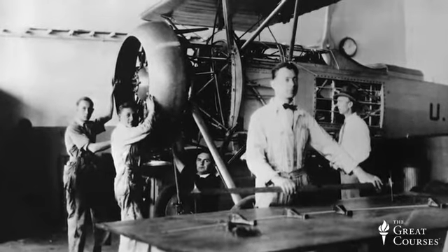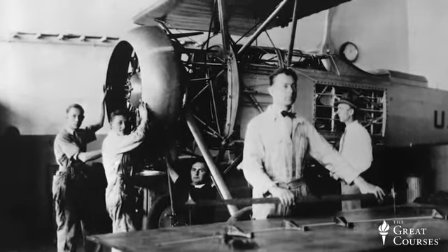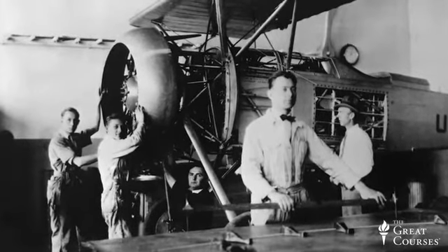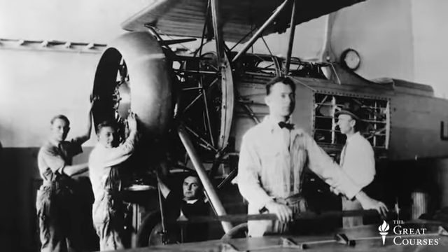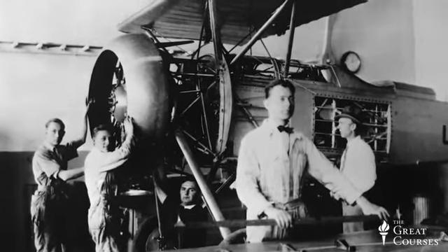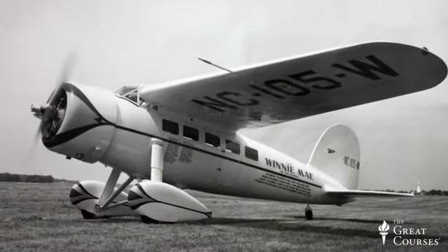Whereas the AT-5A in its baseline configuration had a top speed of 118 miles per hour, with the new NACA cowling, they hit a top speed of 137 miles per hour, a 16% increase in max speed. And on top of that, there was absolutely no change in the cooling of the engine, as the oil temperatures remained the same. This huge jump in performance led industry to immediately snatch up the NACA cowling concept, with the Lockheed Vega being the first aircraft to install the cowling.